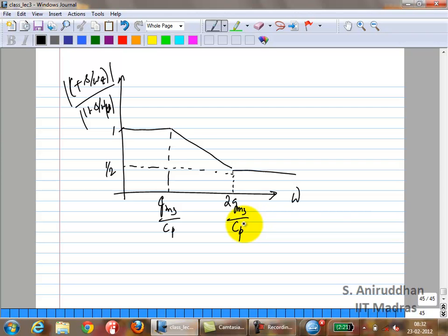Okay, I want you to go and confirm this today, at least now. And how do you decide if it's a left half plane or a right half plane zero? Can you tell just based on this which one it is? You can't. You have to look at the phase shift, right? Anyway, I want you to go and tell me tomorrow whether it's an LHP or an RHP zero. It's a very simple circuit.